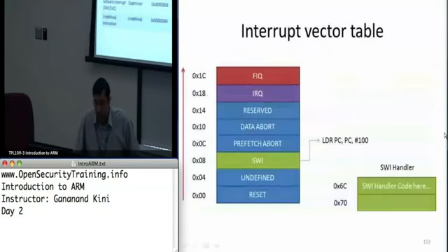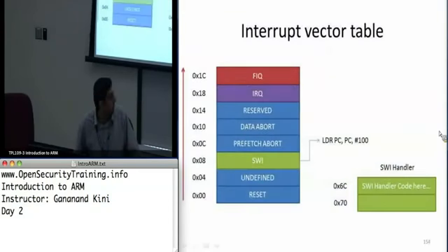So actually this is what it would look like. Your interrupt vector table, the memory, again, I have it increasing upwards. So it starts off at 0. Whatever is located here, some microcontrollers for even ARM will actually just have an address at that location.